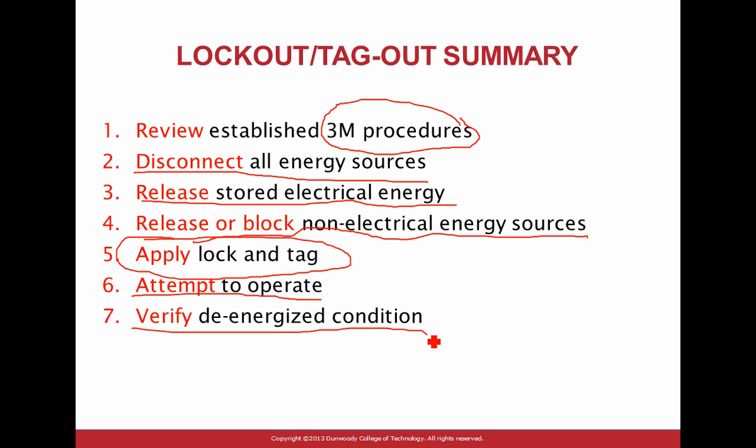And before you do that, what happens if the battery is dead on this and it's not working? So before you do that, you go to an outlet like a 120 outlet, and you put yourself on voltage here, and you go measure, and you expect when you go to 120, what do you get? 120, not 240, and make sure that thing is giving you that to verify the operation of the equipment. That's required by the 70E, verification of the de-energization. After you verify by measuring the voltage is absent from this piece of equipment.